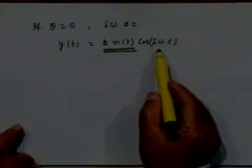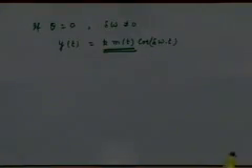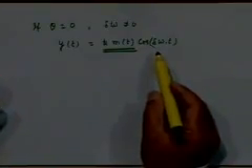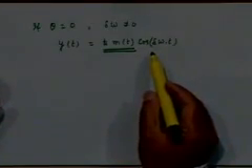But the important case to discuss here is not that case, but the case when delta omega is very small, because that is what will practically happen. You will have a local carrier, you will try to adjust its frequency to be as close to that of the incoming carrier, but maybe there is a very small frequency difference left and you are not able to take care of that, right. So this may be of the order of a few hertz, maybe tens of hertz or at the most hundreds of hertz, right. Typically tens of hertz. If you are using very stable oscillators both at the transmitter as well as at the receiver, the typical frequency difference will not be that high, right, which will be the case in practice.